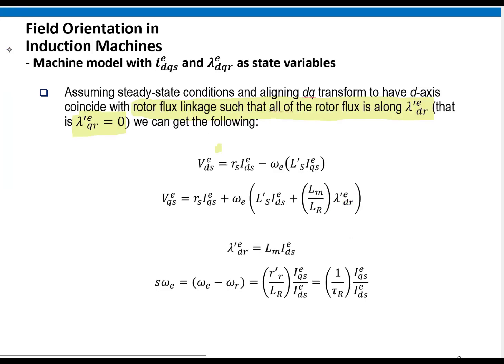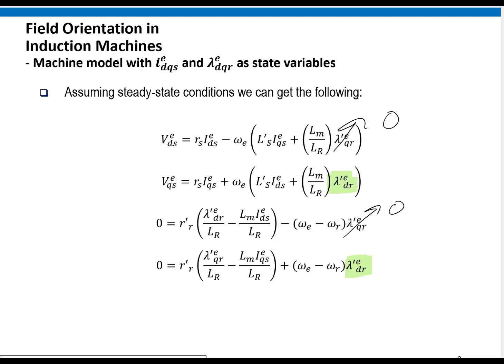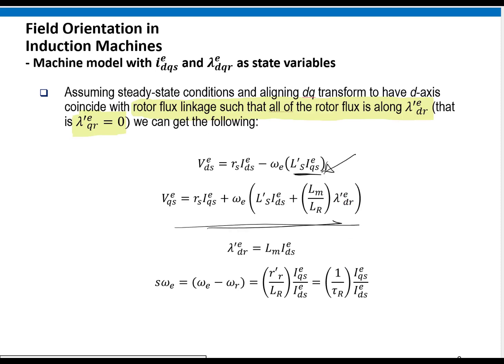We got this term right here, just subtracting off this simple kind of coupling from the q-axis circuit. And then if we look at the q-axis circuit, the q-axis voltage, we didn't get rid of anything. It's the same thing, see? Now, if we do this, the d-axis voltage is equal to the magnetizing inductance times IDS.